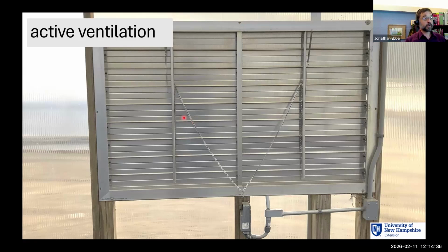One really big thing is that we want to make sure that the intake side, if you have a door that you typically leave open on that house, is on the same side as the door that you want to leave open. I'll show you why in a second, but we don't want that fan next to an open door when you're exhausting, because we drop the efficiency of that fan.